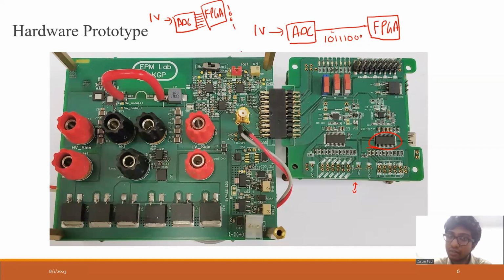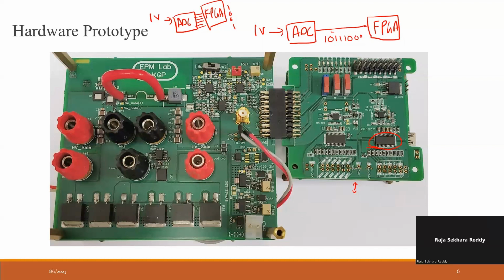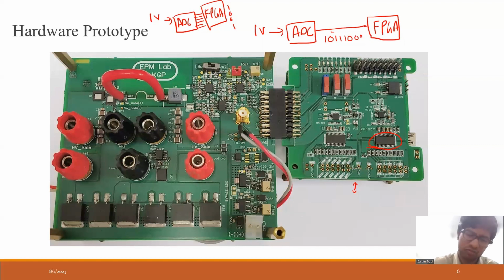Which ADC to use and its requirements will all be taught in the later part of this course. But just for information, the FPGA can only interact with digital signals. It cannot interact with an analog signal. So to feed the real world signal to the FPGA, it has to be processed by an ADC to convert it into digital data, which will then be used by the FPGA for its operation.